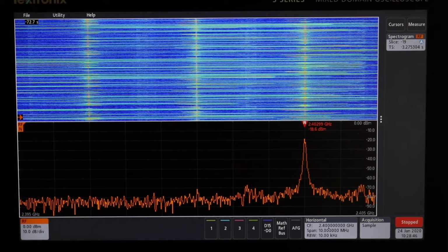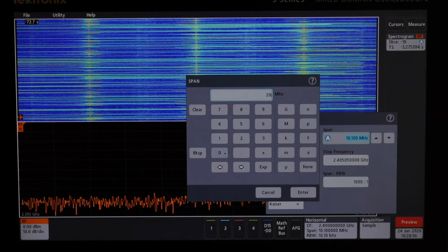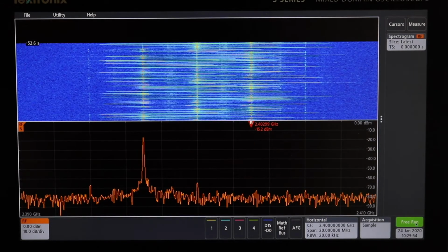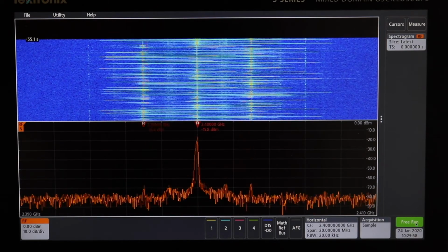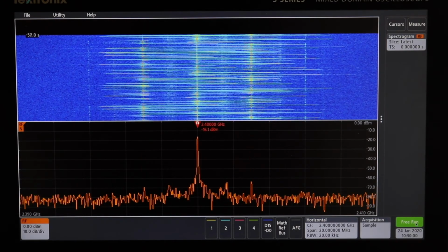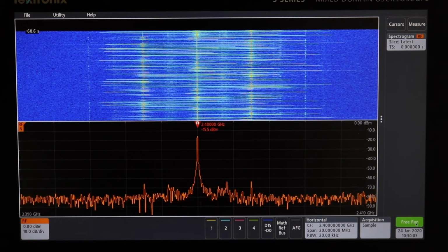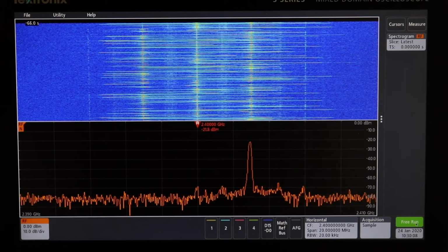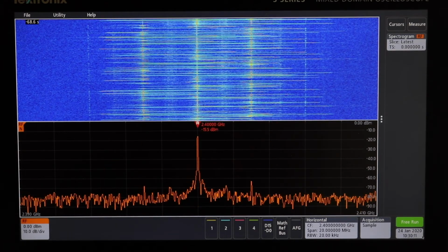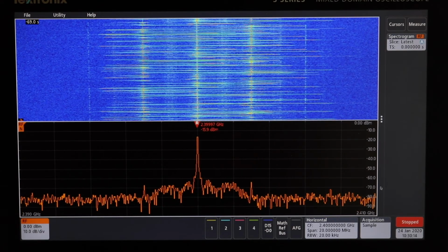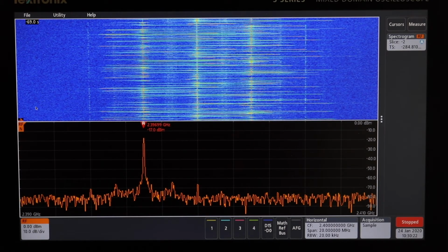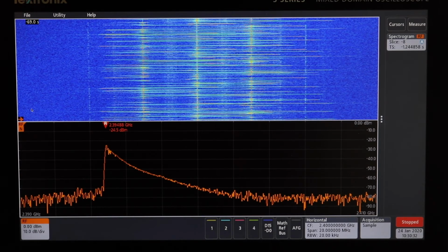It's a 10 megahertz span. I'll just change that up to double the span and see what else is there. Okay, so this is the span now doubled on the frequency hop signal. You can see there isn't much outside. The 10 megahertz is probably okay, to be honest. Give him a stop and have a look through the slices. There it is. So 2.39, 2.4. Yeah, there's not much. Yeah, signal right over there at 2.3948.